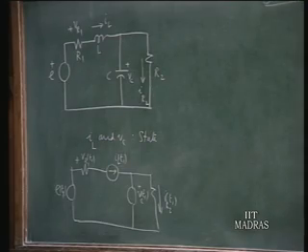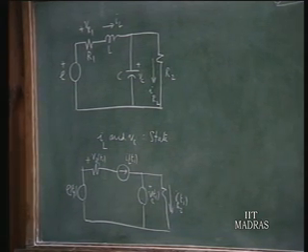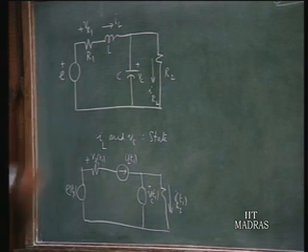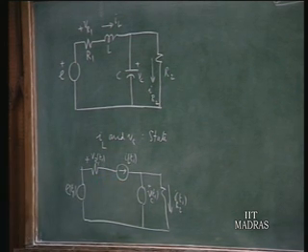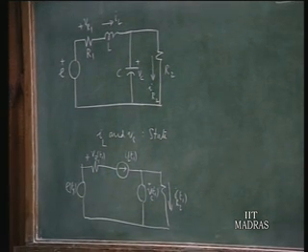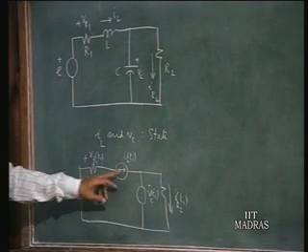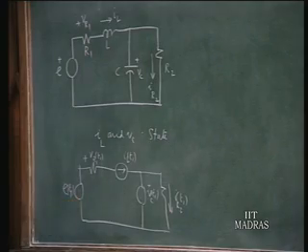So, as far as the state is concerned, then we have two particular points of significance. One is that it is the information we need to know about a system so that we can predict the future behavior under the influence of a specified excitation function from that point onwards. Secondly, once you know the state of the system, the outputs at that particular point of time can be computed purely through an algebraic process involving the values of the state at that particular point and the excitation function at that time.